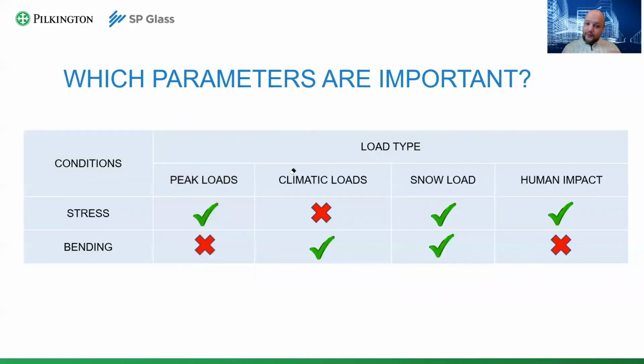On the contrary, if you have climatic loads, for the most part, you will be looking at how your glass will behave. If you take only climatic loads, you will be seeing how much distortion, how much length you will be having on the facade. With climatic loads, usually the most important thing we'll be looking at is bending, not the stress. And now try to remember what I've been saying about load duration. Peak wind loads are very fast, very sharp, so load duration is almost instant. Climatic load is a long time load.